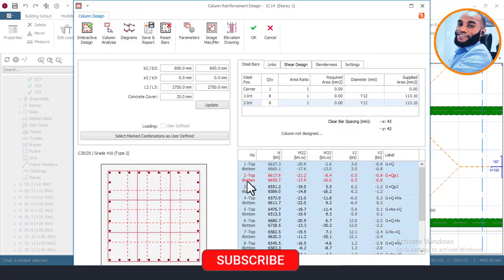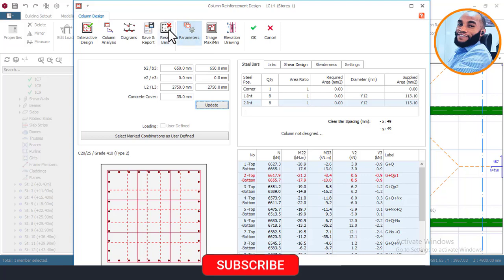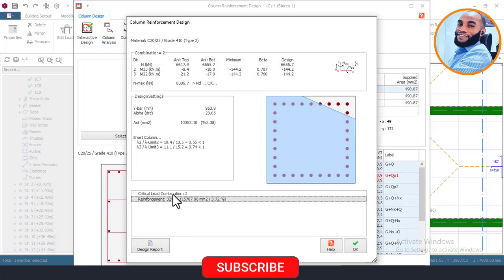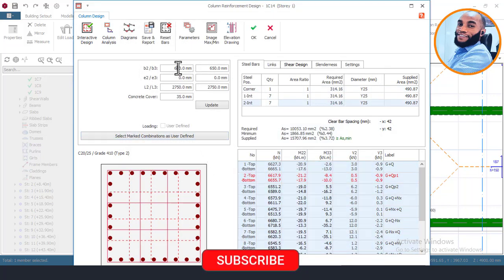I'll come here and say okay, and increase the size to 650 and also 650 here, and then click on update and reset T bars, then click on design and wait for it to run the design, and that is okay. This is showing me 32 number, that's fine, I can do that. And I'll come here and say okay. If I want to, I can go and choose 700. That's to reduce the number of the bars, but I think that's okay basically.